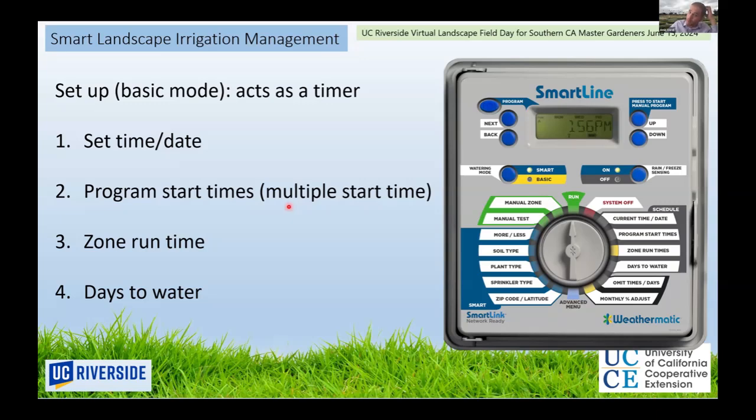I often see in my neighborhood that people irrigate in the morning. So part of that water goes right back to the atmosphere. So evaporative loss, because the sun is already out. And usually, based on my experience, the wind speed is lower overnight. So you avoid evaporative loss and also wind drift.